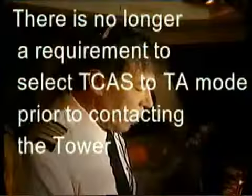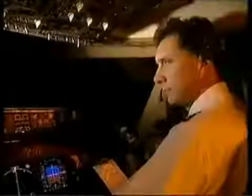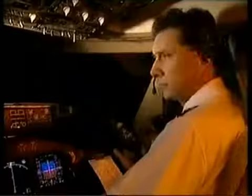Special procedures on the All Users page are, if we get an ATC breakout instruction, I must disengage the autopilot and hand fly the procedure until stabilised on the breakout heading. Now your job will be to acknowledge the breakout instruction and monitor the flight path and speed while we reconfigure the aircraft and set the breakout heading and the assigned altitude. Any questions? Is it possible to get a descending breakout? That's unlikely, but if we have a descending breakout, we will not be required to exceed a rate of descent of more than 1,000 feet per minute.